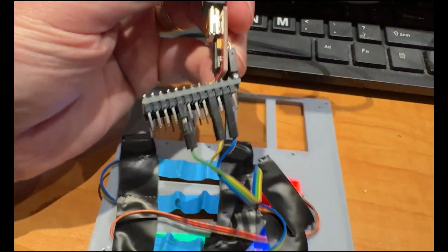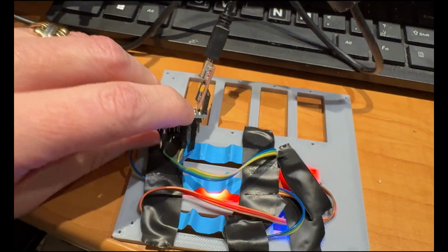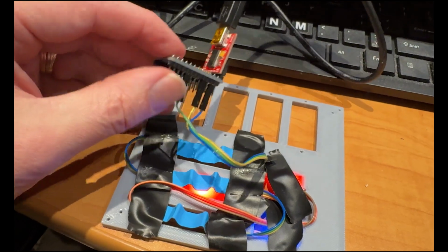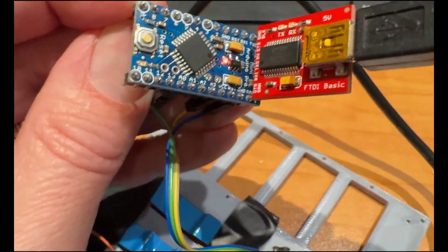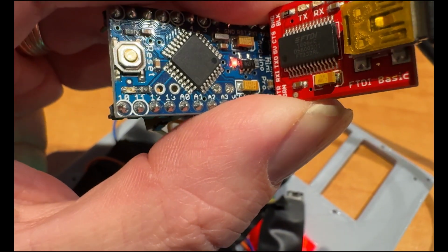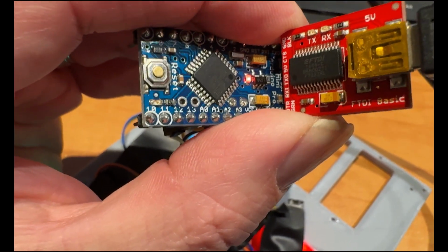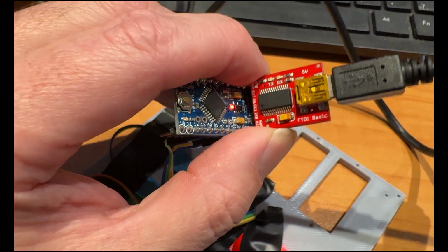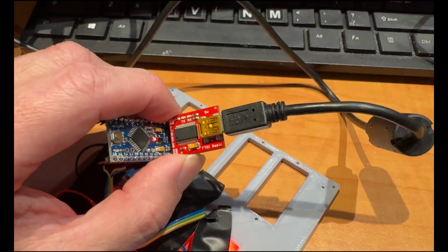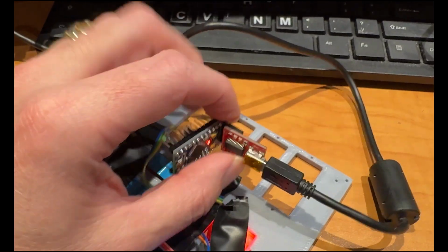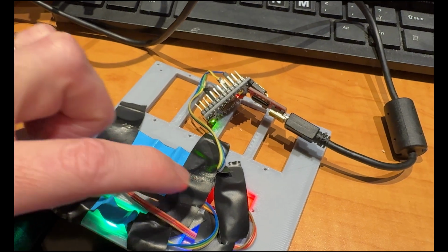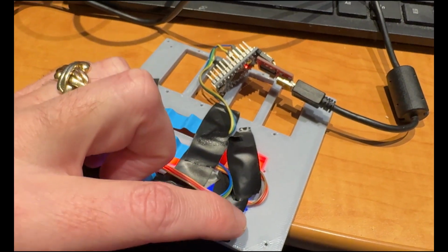The pins I'm using are ground, then VCC for power, and then this is pin 14. It's beside 13. It's actually called A0. So you can see the 10, 11, 12, 13, A0. That's actually pin 14. I use that for some reason. And you program it in the Arduino IDE using this thing. You pick the COM port. There's videos on that. But it comes in here, does this, and then hits this one and that one.